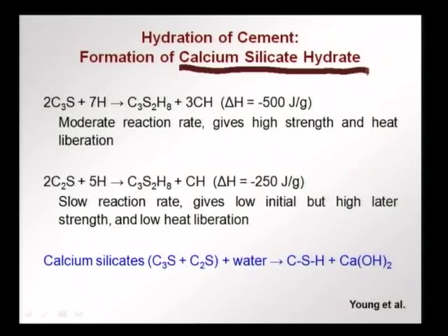First to react will be the C3S, and here you see the reaction. C3S with water gives us the calcium silicate hydrate and calcium hydroxide along with the emission of heat. This is a moderate rate reaction. It gives very high strength early on and there is a lot of heat liberation.